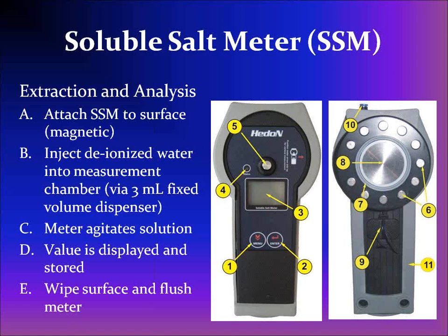Thoroughly flush the meter using water from the dose bottle so that it is ready for subsequent measurements. The stored values can be uploaded to the data management software using the USB cable.